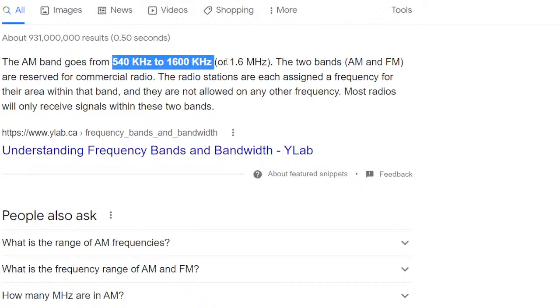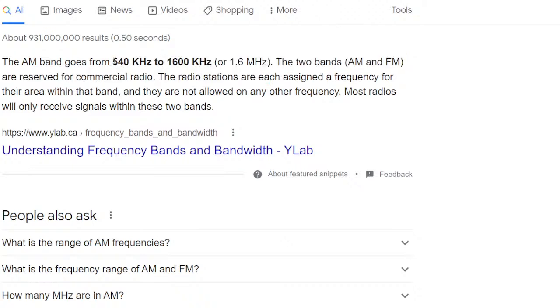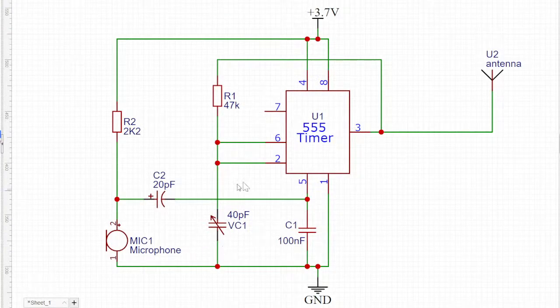All right, so you want to design the 555 timer in an astable mode to oscillate at this frequency or within this frequency. So you have to know what components are responsible for the oscillation. And in our case, it is the resistor and the capacitor, the R and the C. Now, if you want to build a transmitter that works within a range, then you have to have one of the components that play a role in the frequency be variable.